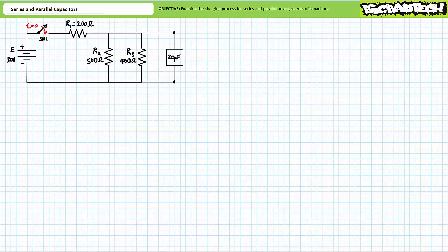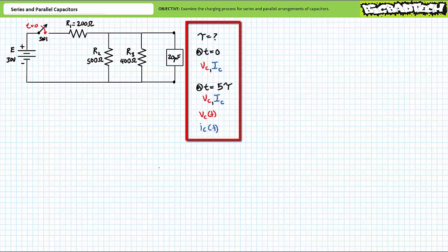Analysis of this type of charging circuit is a skill you've had ample experience with by now. As such, I leave it to you as an exercise. If you need a task list, here it is. Determine the Thevenin's equivalent circuit seen by the initially uncharged capacitor. Determine the time constant for the charging process.